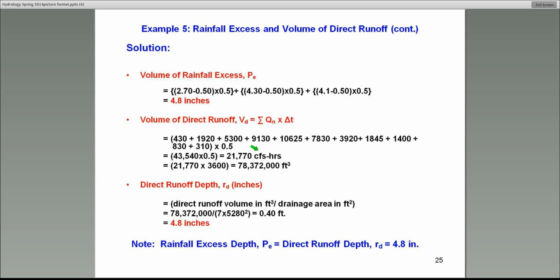Now you remember this unit, I told you about the SFD, I've mentioned that unit, but I did not mention a CFS-hour. That's one CFS flowing for 1 hour, by the way. Therefore, using that 1 hour of 3,600 seconds, I can convert that to cubic feet.